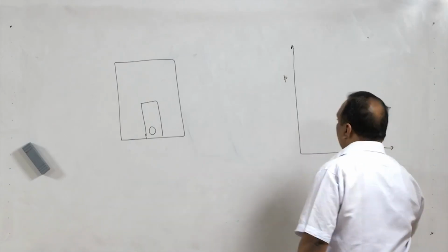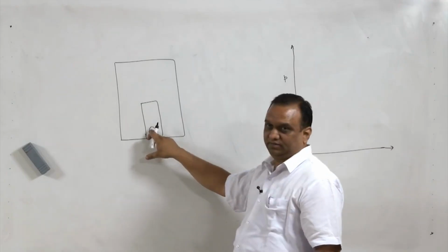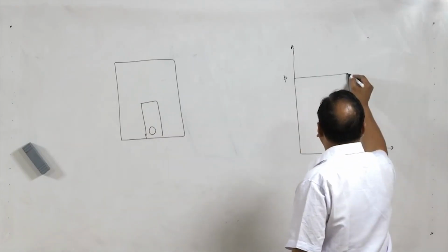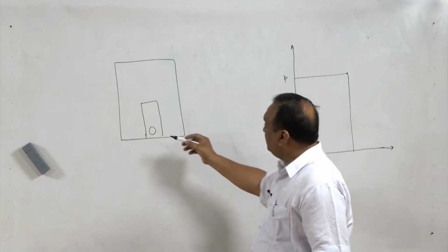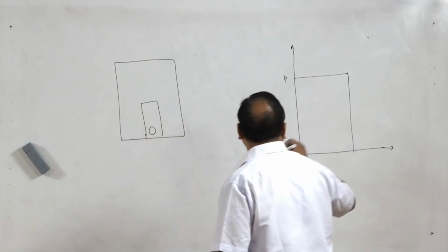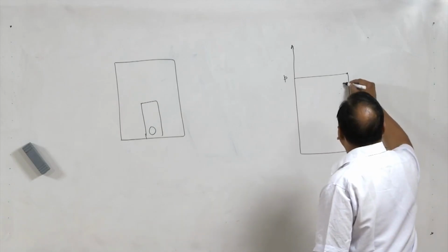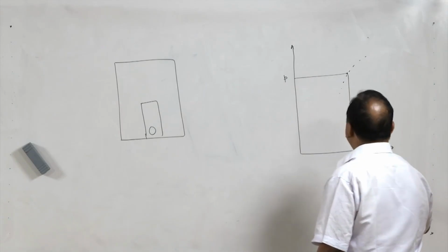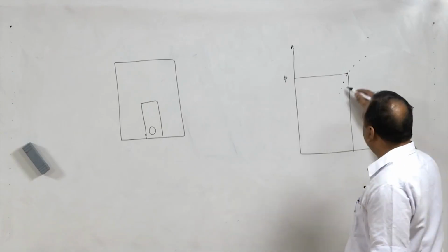It is noted what the flow rate of this blower is in order to maintain that pressure, and we get 1 point. Now we keep on changing the pressure above the atmospheric pressure, and we get different points for different pressures. When the pressure is high, flow rate will be high. When the pressure is low, definitely flow rate will be low.